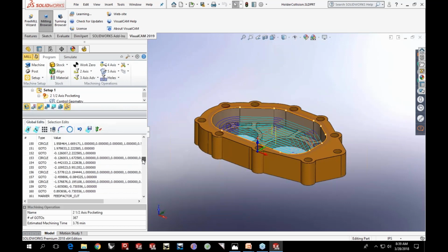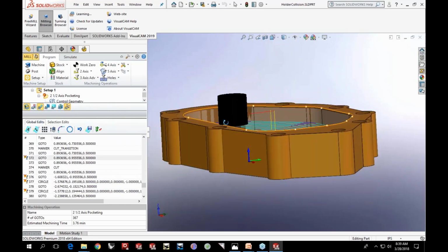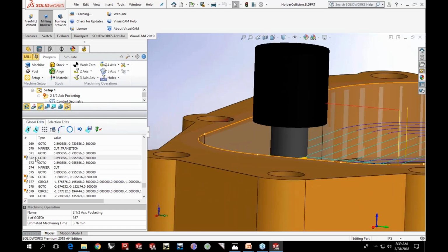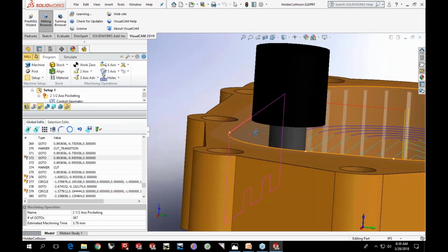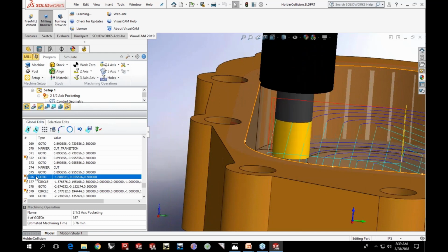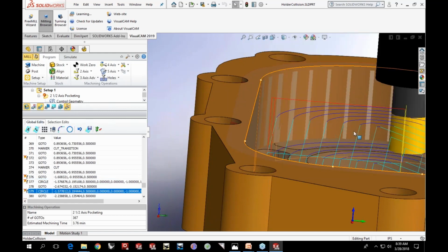So as you scroll through your toolpath viewer, which is available right from our standard configuration, or the toolpath editor, which is included in Pro and Premium configurations, you will see that it marks the go-to motions where you run into a holder collision. So here you can see that these lines in here would result in a holder collision, and it also automatically marks those collision areas in the toolpath viewer or toolpath editor. So for each of the areas where there's a holder collision, it'll mark it.